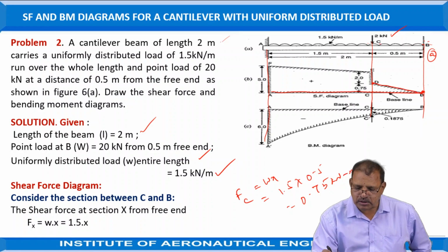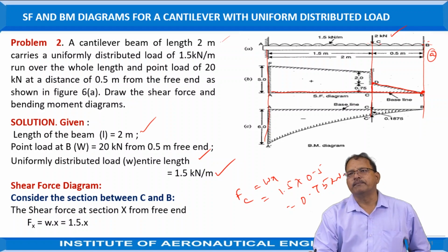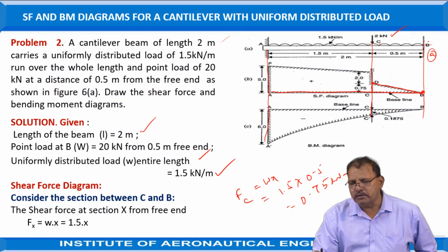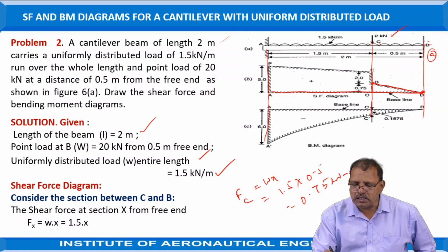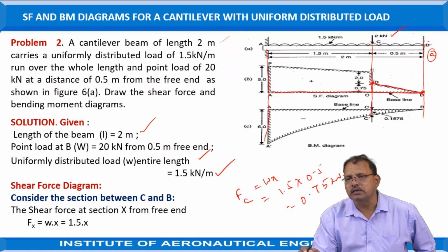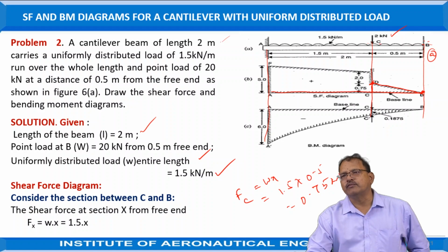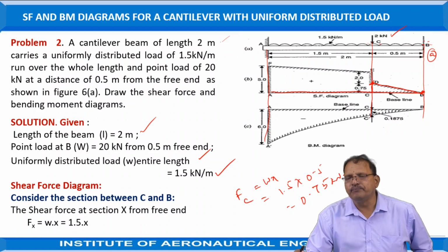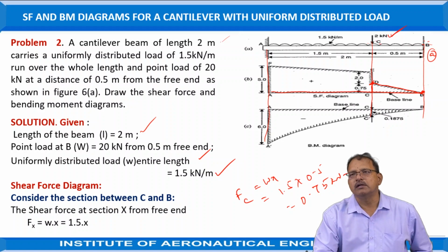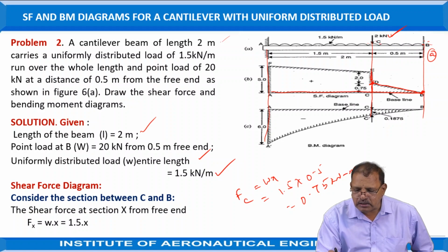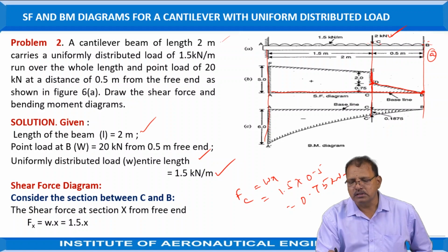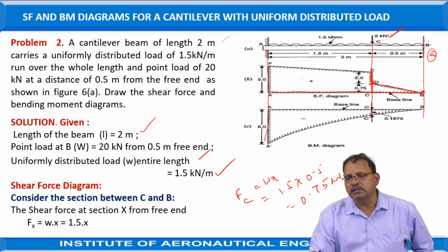So you have to draw it according to the scale, just 0.75 in the upward direction, and represent it. Here we are taking 1 kilonewton equal to 10 centimeters, and so 7.5 mm. Just take it and draw the vertical lines. Join D and C, B. This is known as the shear force diagram. But at C, suddenly again a 2 kilonewton force is also acting. So draw vertically an additional 2 kilonewtons, that is 2 centimeters upward, to represent the total shear force that is acting at C.